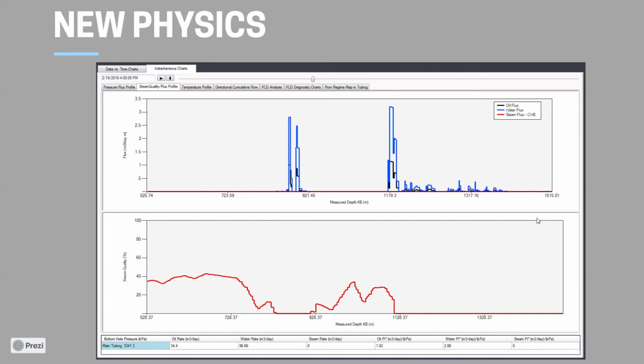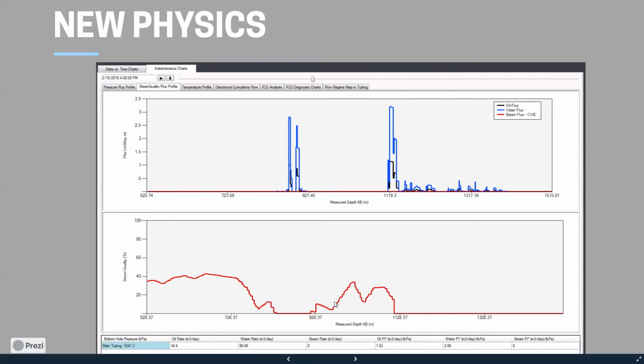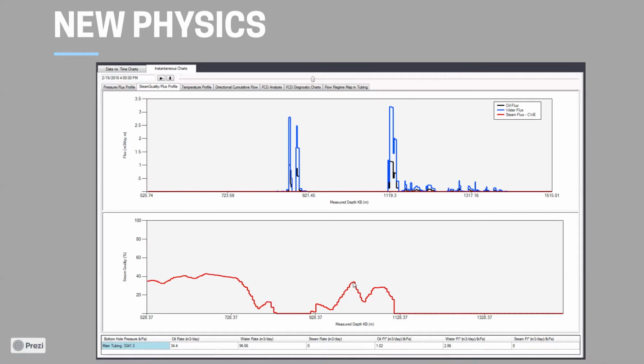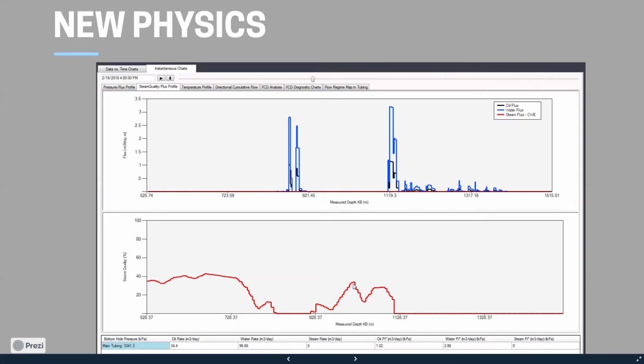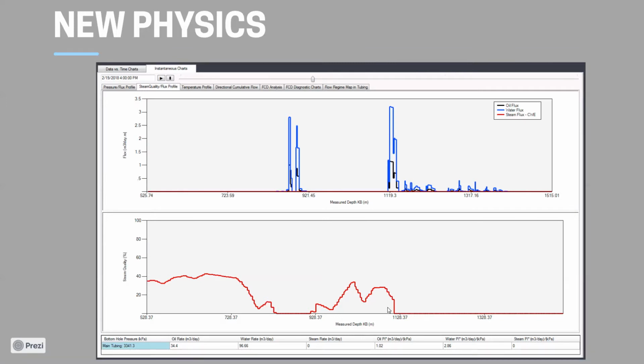For example, in thermal operation, we do have steam coning. Once you run at very high temperatures, the producer, and you suck at very low pressures, then the result would be a steam flash and a steam coning at the edge of the wellbore. And you see here the steam quality created and start flashing and start breakthrough. And as a result, the mobility of the liquid phase goes close to zero, and reduction of the production happens. There is no software in the world that captures such a phenomenon, and this is the only software in the world that can capture it.